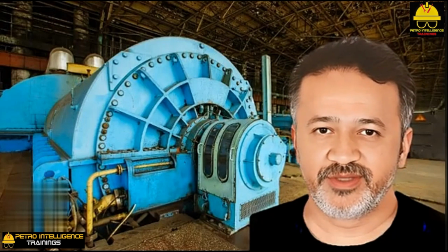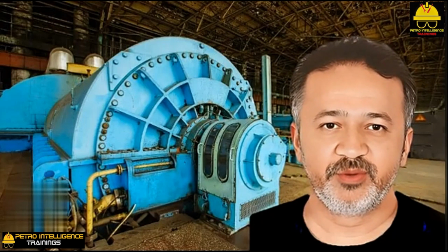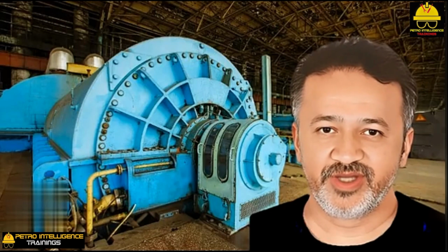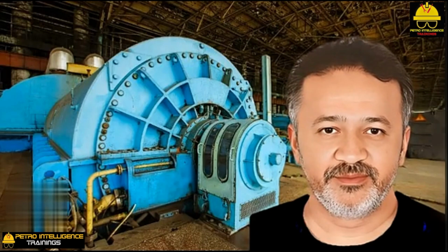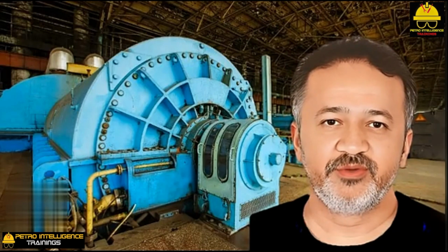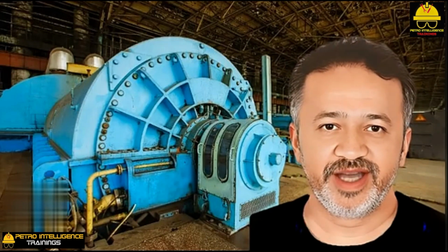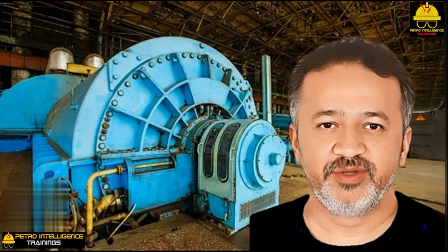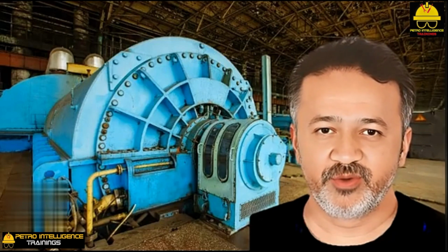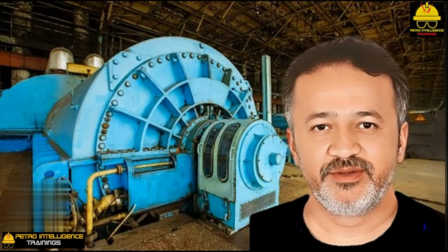But for what purpose? Let's say a turbine was using 400 psig or 415 psia steam exhausting to a 30 psig or 45 psia steam header. The work generated was 2000 horsepower. If we had condensed the steam at 76 mm of mercury or 1.5 psia, the work generated would be 4000 horsepower.